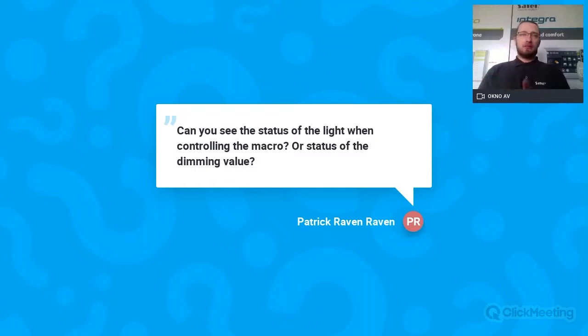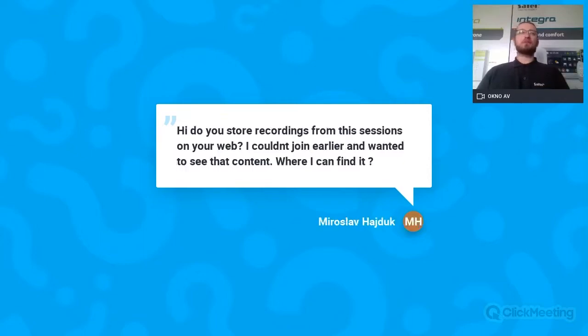I know this sounds a little bit tricky, but yes, you can do this. And then you can receive information about only a switch status, so 0 and 1. You can't use dimming for it because you won't be able to receive like 50% inside the INTEGRA panel. It works only as 0, 1 in general. So there is a way to do it, a little bit around, but yeah, it works.